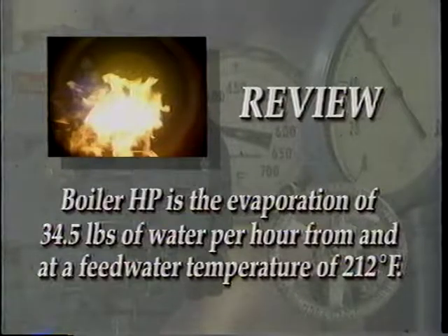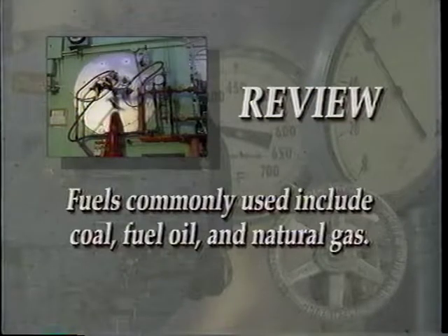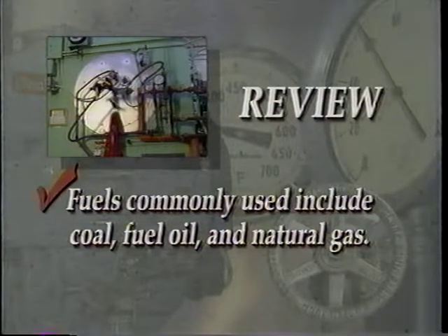A boiler horsepower is the evaporation of 34.5 pounds of water per hour from and at a feed water temperature of 212 degrees Fahrenheit. Fuels commonly used to generate heat to produce steam in a boiler include coal, fuel oil, and natural gas.